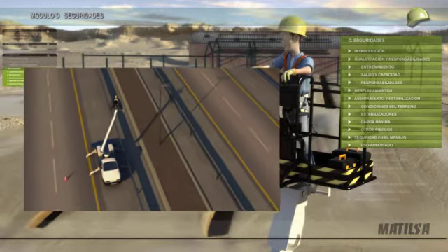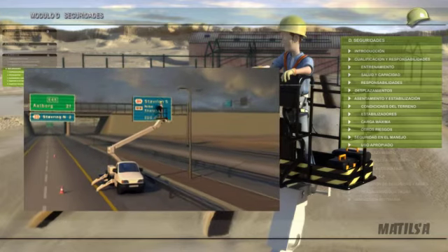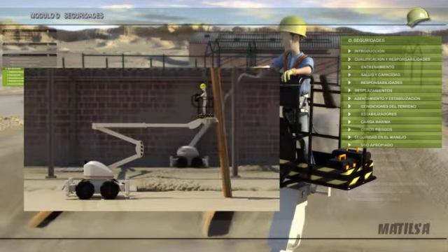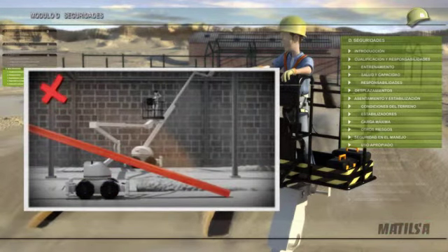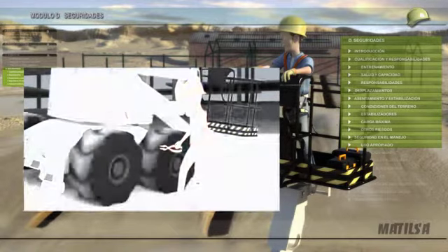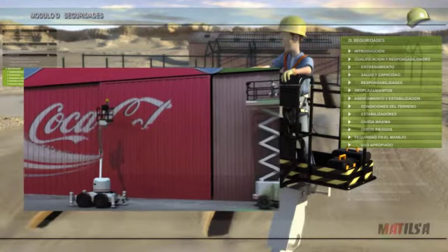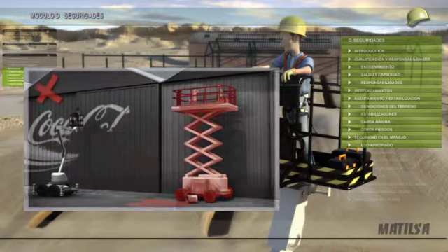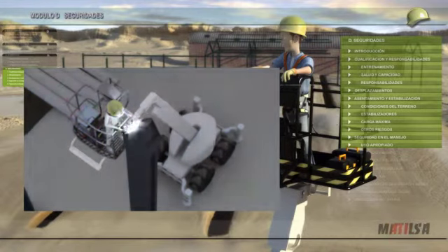If in your working area you come across other vehicles, make sure that you place cones or signals to prevent possible accidents. If in doubt, consult your managers immediately. Do not lean on other structures or use the platform as an elevating hoist. You should never modify or cancel the safety systems. Avoid damaging the machine with pieces of brickwork, painting, sand, red-hot pieces of iron or welding. Do not use the platform as an earth connection when welding.